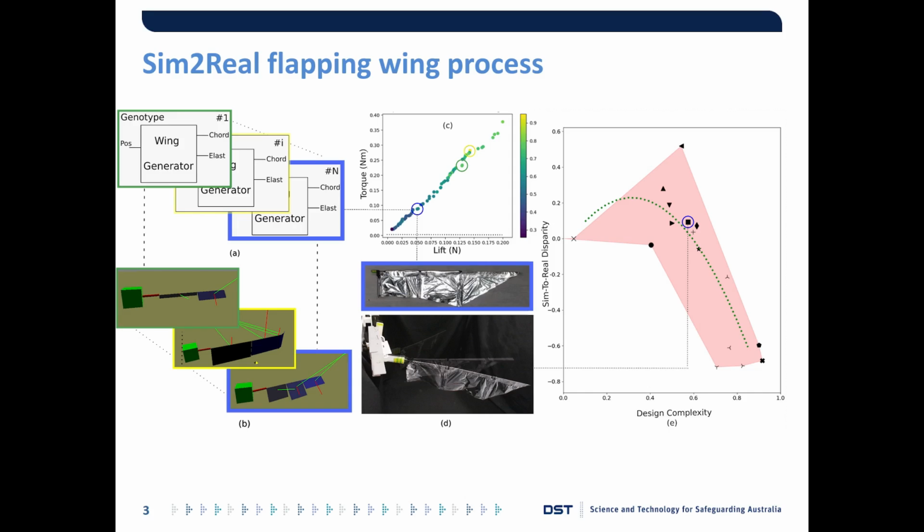The ability to produce simulations that match reality for arbitrary behavior and morphology exceeds currently available physics simulation packages, and when we consider the effective material properties, non-homogeneous materials, stiffness, aerodynamics and friction, to name a few, it is easy to imagine a range of ways that robots designed in simulation can produce behaviors that will differ from those seen in reality. To begin to address these gaps, when morphology is not fixed, which we call morphology in the loop design, we seek an understanding of the shape of its reality gap.